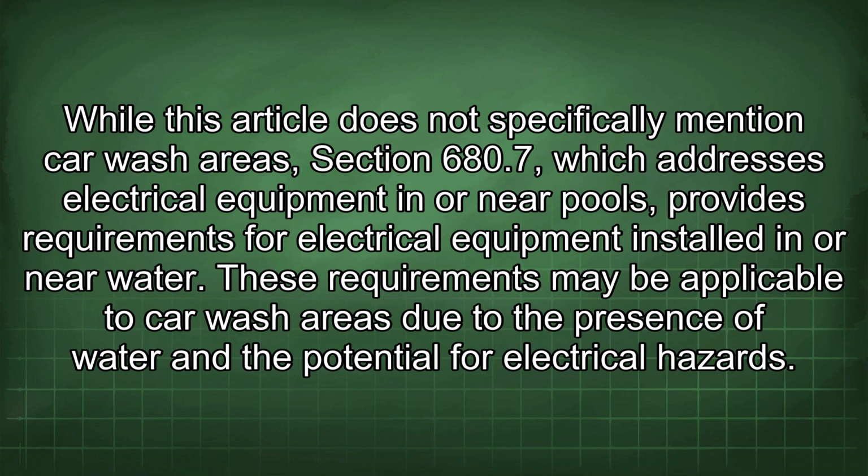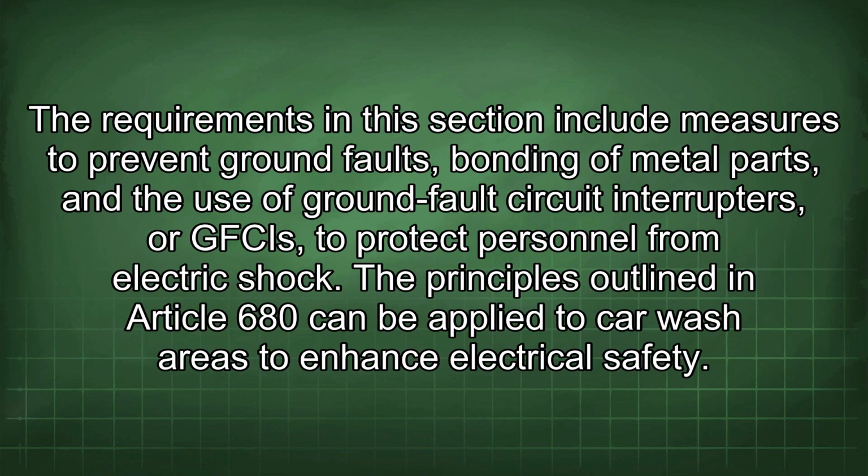These requirements may be applicable to car wash areas due to the presence of water and the potential for electrical hazards. The requirements in this section include measures to prevent ground faults, bonding of metal parts, and the use of ground fault circuit interrupters, or GFCIs, to protect personnel from electric shock. The principles outlined in Article 680 can be applied to car wash areas to enhance electrical safety.